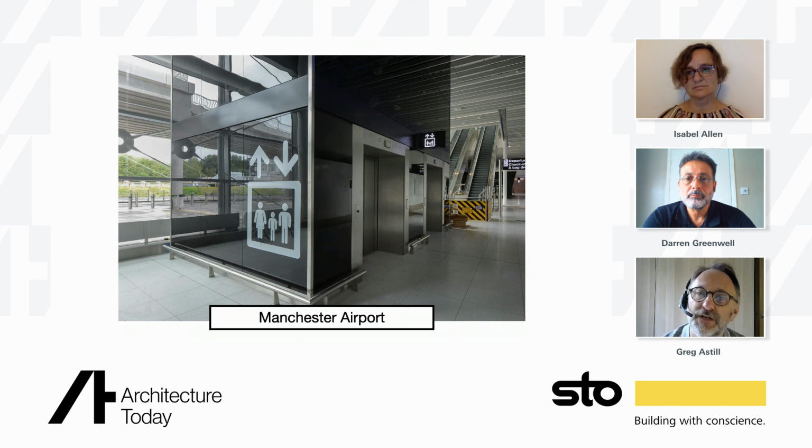So here you've got the signage on the side of that part of the building showing the elevators, which I think was back printed. But we also have other signage in other areas where the glass was actually cut out to receive an acrylic sign into it, which was backlit. And there are other areas where we've just had holes drilled or formed the glass with holes in, so that support brackets for suspended signage can come off, and you can also get the power cable through those openings that we've made to also backlight those parts as well. So that was quite a challenge.